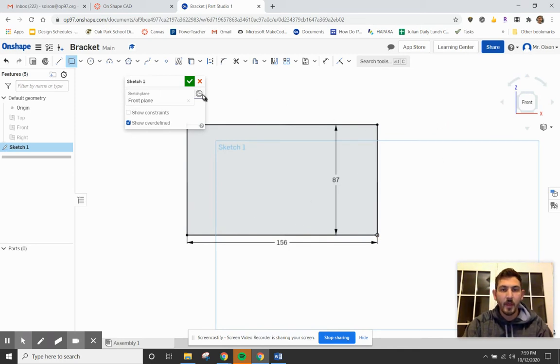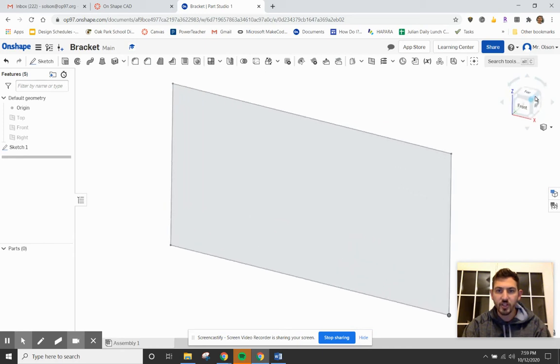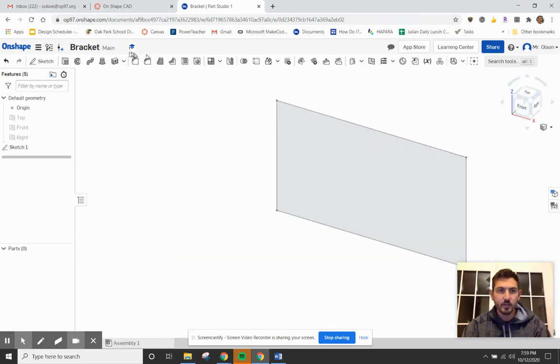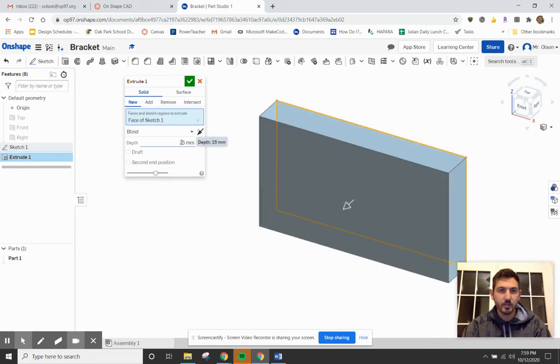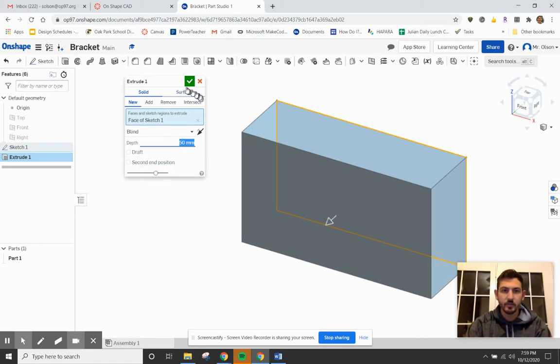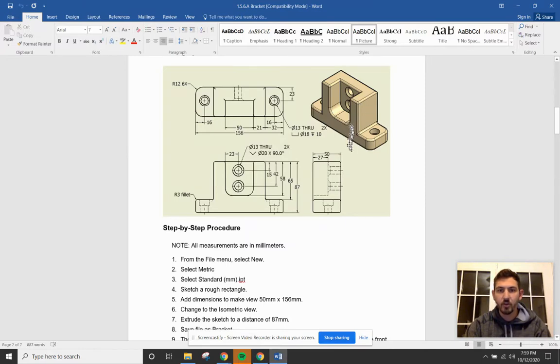All right. So I'm going to finish that up. I'm going to turn this into a 3D shape. So I'm going to extrude this now. And my extrusion should be by 50. So I'm going to click on my object. Right now it's like 5, I'm going to go 50 millimeters. Enter. And there I got, and you should hopefully be able to see, all right, now I already got this rectangle shape here. Okay.